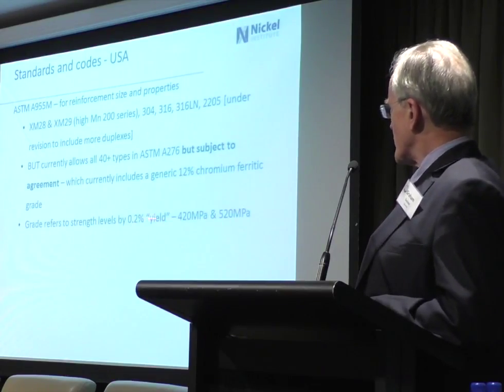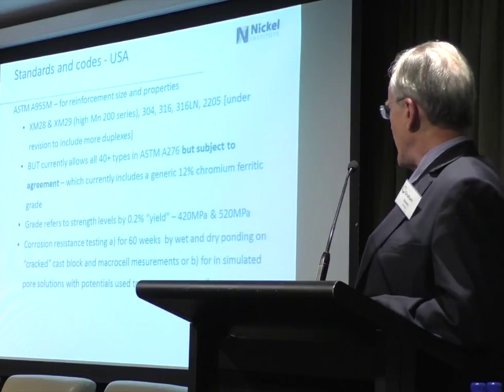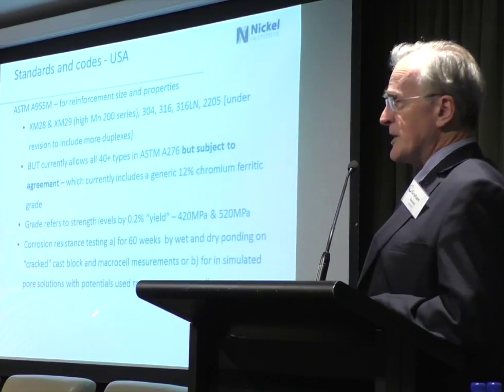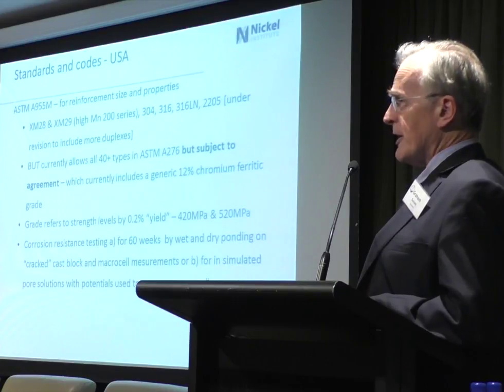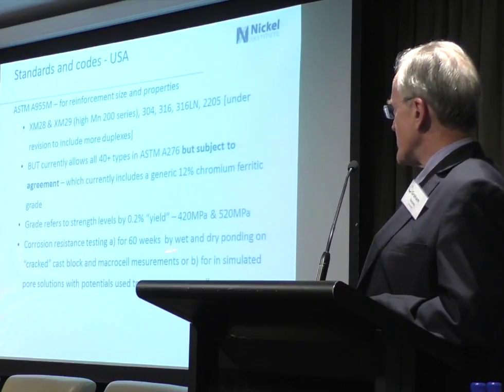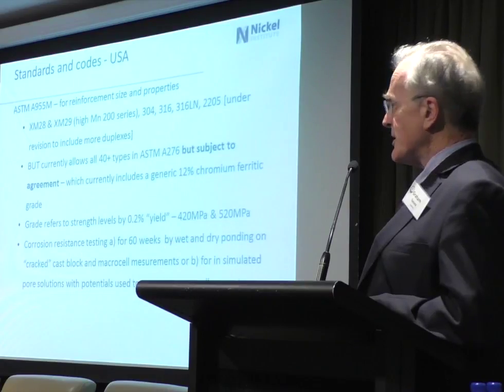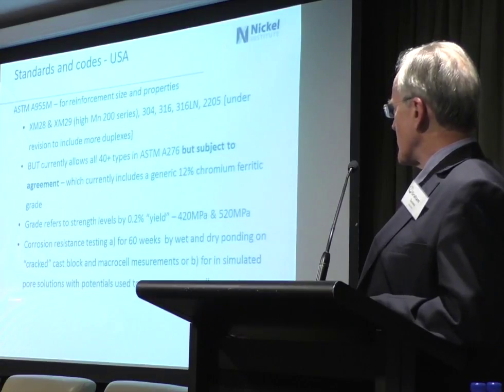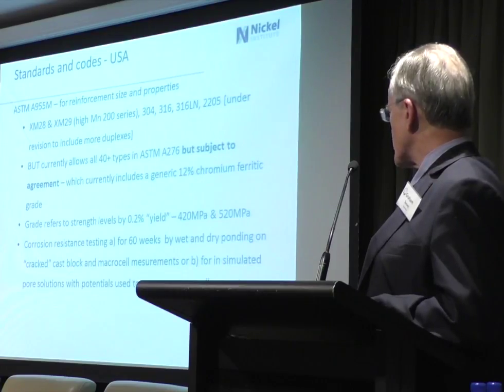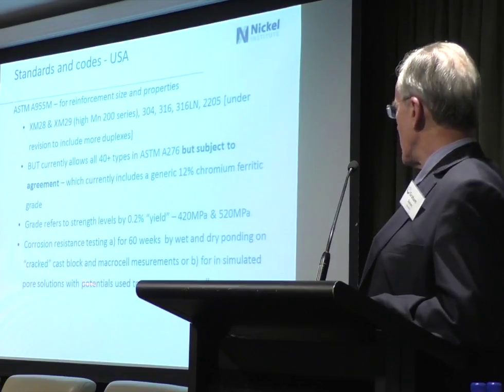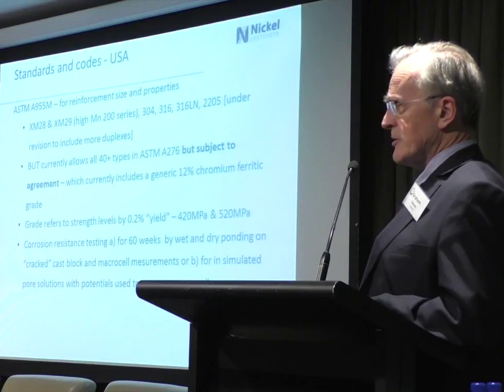There are 2 different grades, and for corrosion resistance, the standard has a means of qualifying other alloys: a 60-week wet and dry ponding test, or a simulated pore solution for, I think it's 15 weeks, looking at macrocell currents.